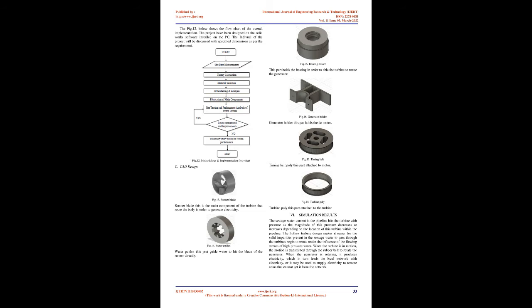Because if these impurities cause blockage in the turbine, this will affect the overall performance of the turbine. Therefore, Pico turbines having a hollow circle around the central axis will be used in this project so that impurities may pass through this hollow structure and may not cause turbine blockage, which would affect turbine performance. Fig. 7 shown below is the design of the hollow Picohydro turbine which was installed at Toyagawa River Basin Sewerage, Japan.